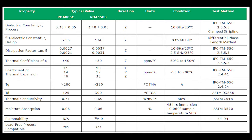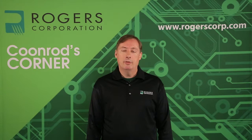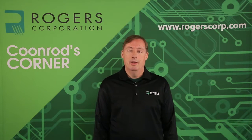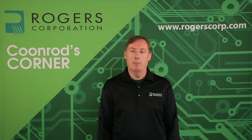Then the thermal conductivity, you can see with both these materials, is also very good, 0.69, 0.75, and then the moisture absorption, again, very low. So this is the standard product, and when you apply the LoPro technology to it with smooth copper, none of these properties really change. They all remain the same. Over many years, Rogers has done a lot of studies on copper, copper treatment, copper roughness. We've come to understand this topic very well, and if you want more details, there are several papers on our Technology Support Hub that can give you a lot more detail.